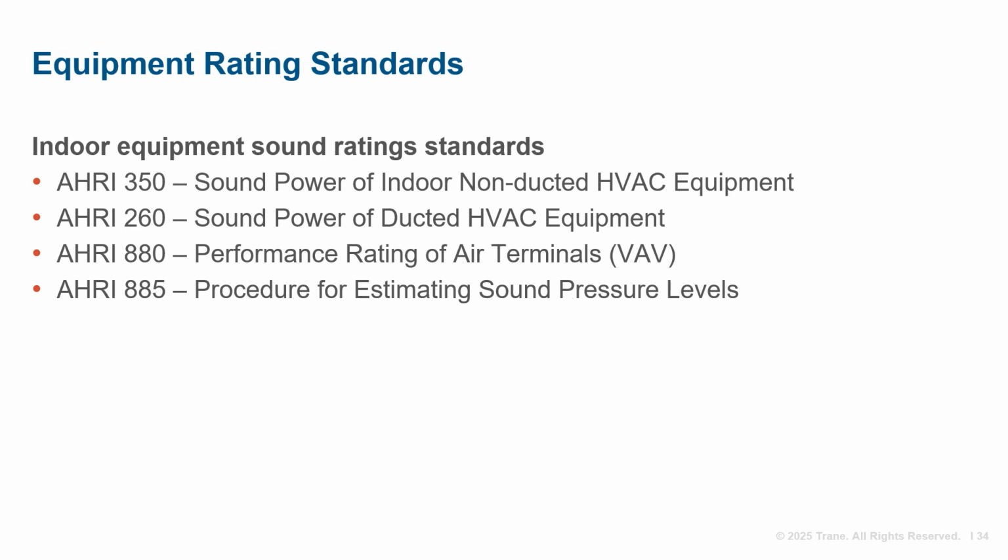880 is a performance certification program, which includes acoustics and also specifies how manufacturers can publish NC ratings of their terminal products by utilizing methods outlined in AHRI 885. Now that's a lot of letters and numbers to throw around, but don't worry, we'll review them in enough detail for you to understand how they are useful in designing quiet spaces.